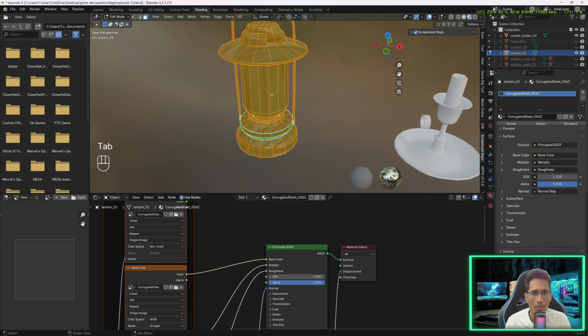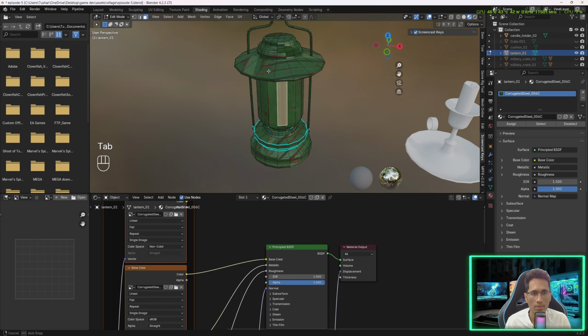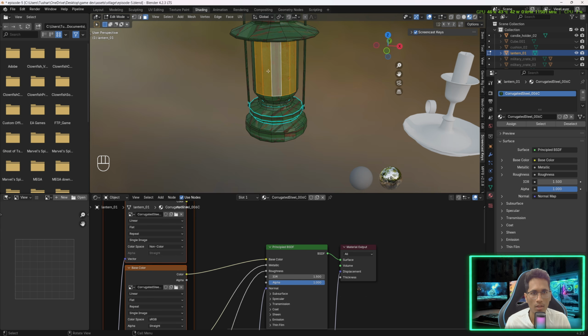Okay, now we would like to change this area into a transparent glass so that light can be visible. However, you cannot create the glass material here in Blender. If you do that, then it cannot be converted into Unreal shader nodes. Okay, so the Blender shader nodes and Unreal shader nodes don't match. So either you bake it and then import them. Other way around is you create the glass material in Unreal Engine. So that's what we are going to do, but we are going to create a material so that we can